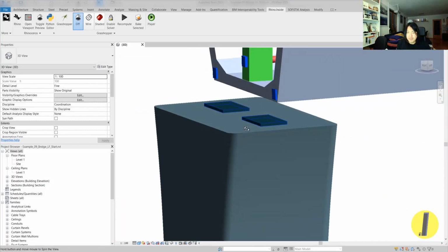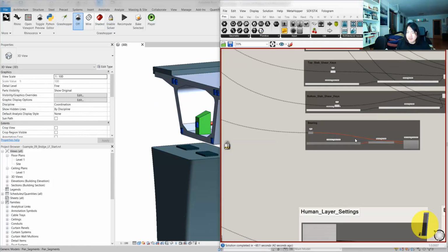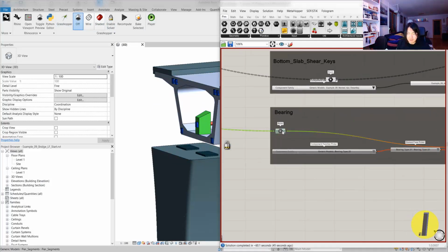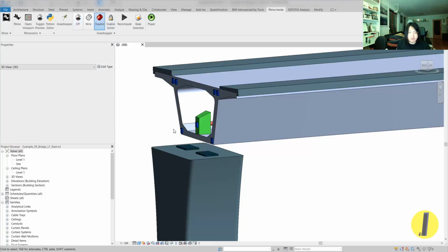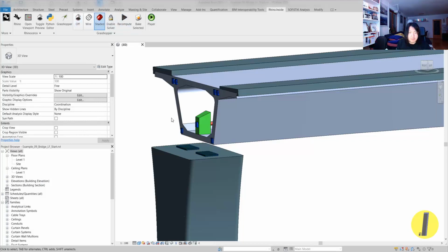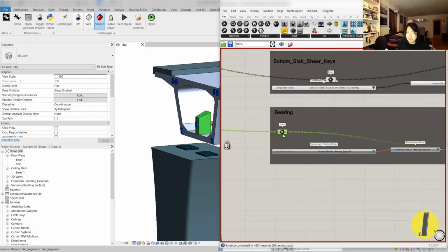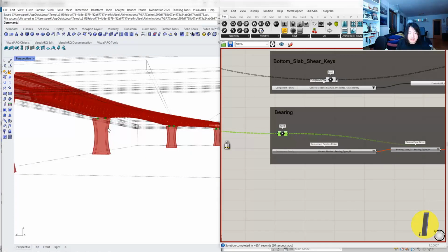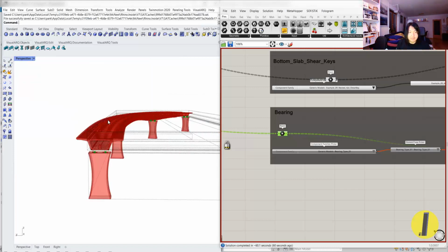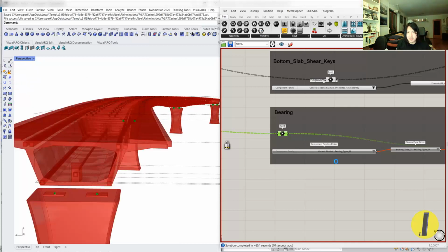The bearing position we can create. So let me go back to the Grasshopper definition, and in this case we're going to use the position of the bearing location. When I turn on the preview and recompute, let's go to Grasshopper, and when I select the point, let me see it in the Rhino view. At these points, we're going to place our family element. Okay, so these green points are the bearing positions.